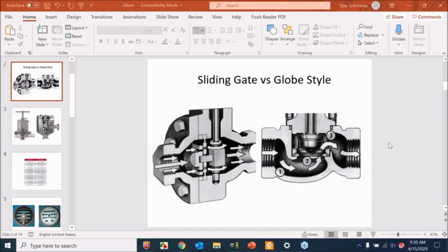So if we're reading 50 PSI and this valve's oversized, trying to operate at 5% open, it's going to fluctuate 48 to 52, not holding tight at what the desired reading is supposed to be. So it just doesn't operate well right off of the seat, and then when it's basically full open, over 90%. So good note there, Chris.